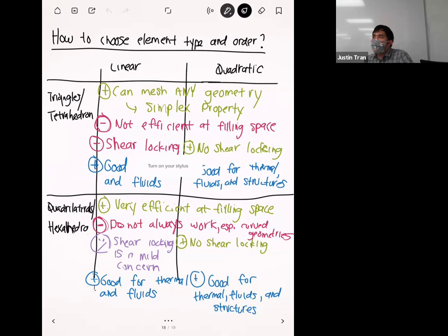Yeah. So sometimes it's impossible to put hexahedrons and quadrilaterals on everything. That's why the name of the setting is hex dominant. ANSYS will try to put as many hexahedra as possible, but for some cases where it can't, it'll switch to triangles. Another thing too is that if you added any refinement object, the refinement doesn't work with the hexahedron, so if you use any refinement, it's automatically going to convert.